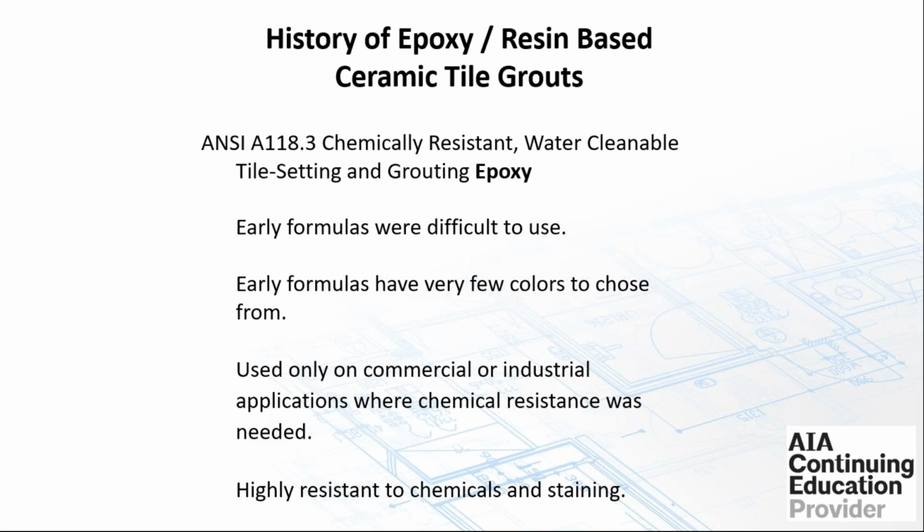One of the things I want you to be very much aware of: an epoxy grout is not a waterproof grout. Believe it or not, I had a call not too many weeks ago from a company that said, we're ready to install the grout, and what grout is waterproof? Isn't the epoxy a waterproof grout? If you're thinking that your grout is going to waterproof your job, you've got a problem.